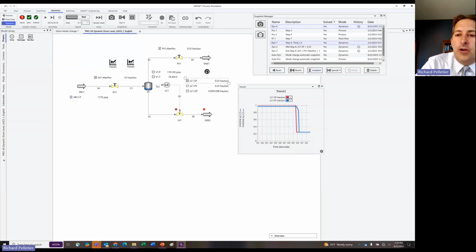And so when I revert to a snapshot with run history, it brings me to that final solution state and has all of the run data in it. Right, so this is a great way to be able to get all of the information for the run back. Right, however, when you have a snapshot with solution history, that's going to store a lot of information, right? Because every single time step is another solution for the entire simulation.